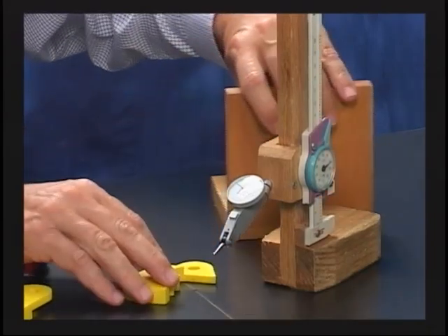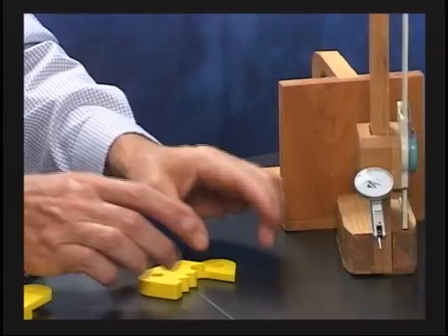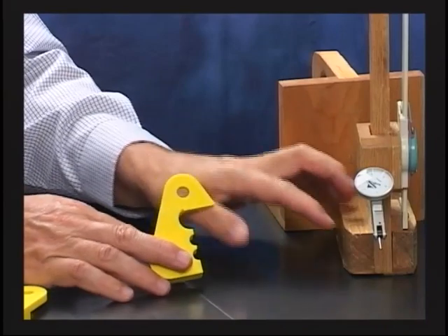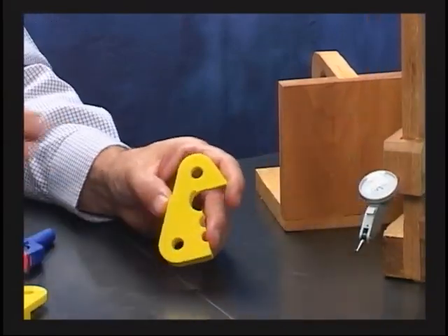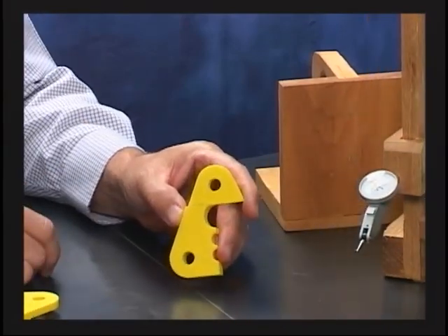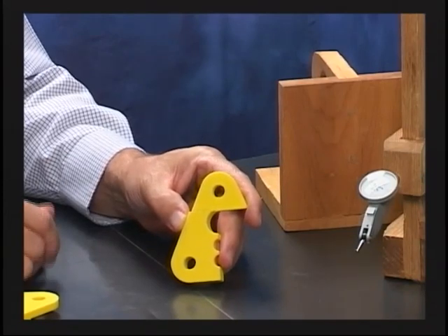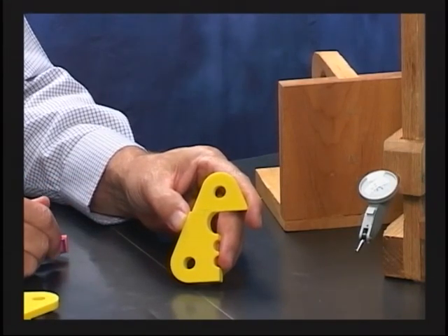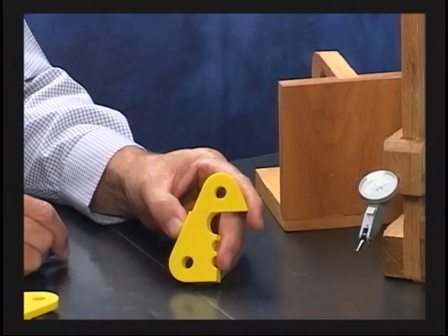Supposedly I could just come in and measure some certain things with calipers. This geometric tolerancing doesn't tell you how to measure anything. It just tells you in theory what it's supposed to look like. And then how you're going to measure it, how much risk you want to take, what kind of procedure, that's up to the quality department to make their decisions about what they're going to do.